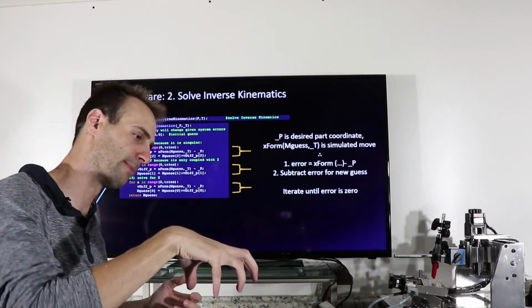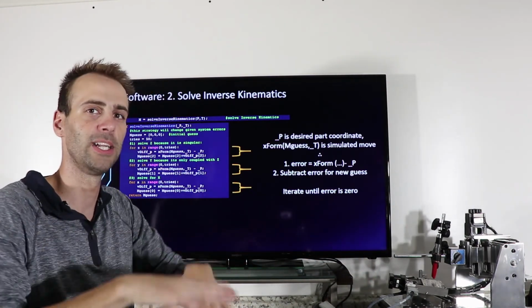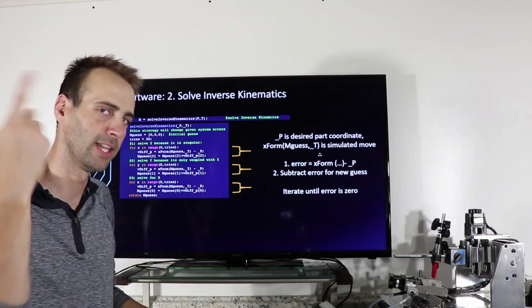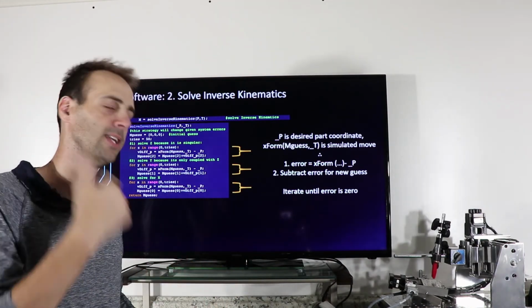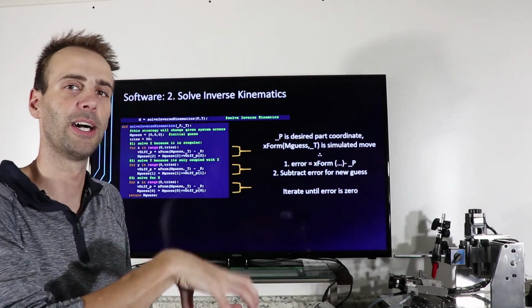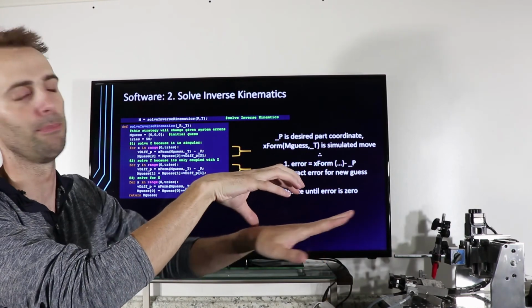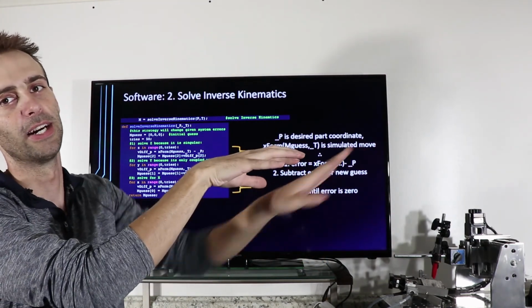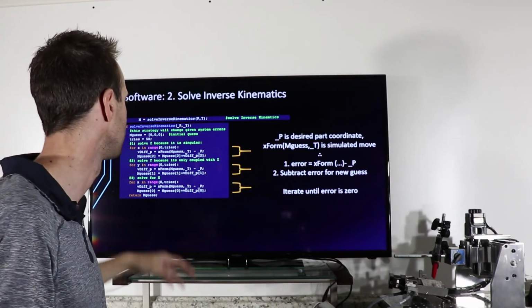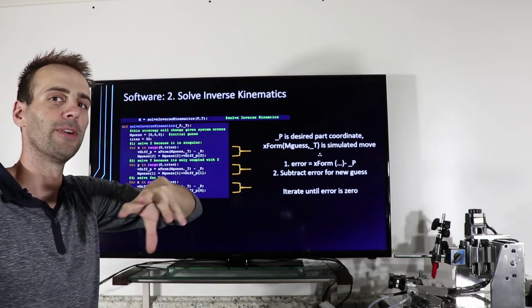So where I put my block already is in the plane of the xy table, right? That's just kind of where I define it. And that's an advantage of decoupling all the errors. So you may or may not have that when you set your gauge block on the tool because the table might not be perpendicular, right? Like if this is the table, the y-axis might shoot down or something like that. So this may not work for you.